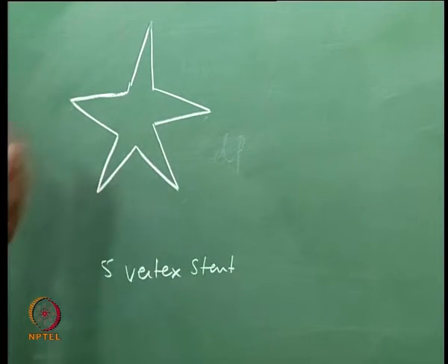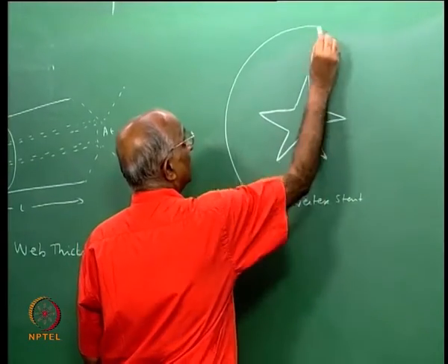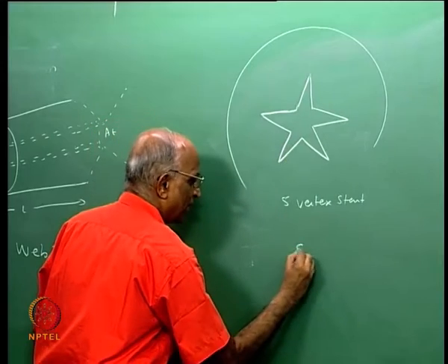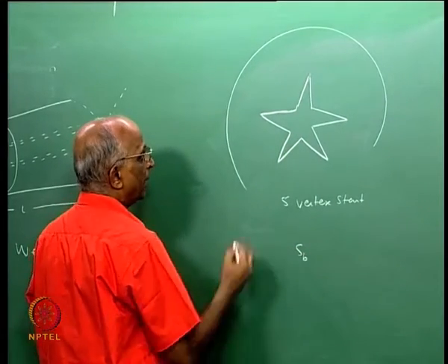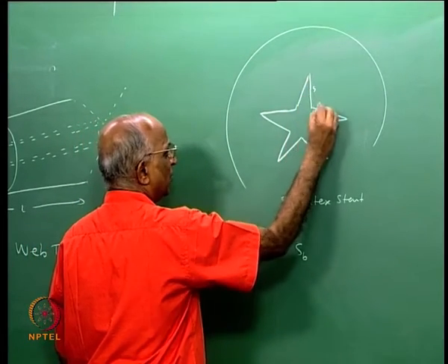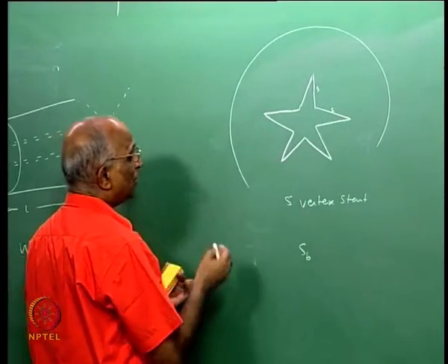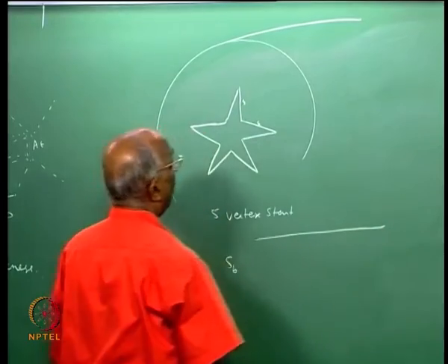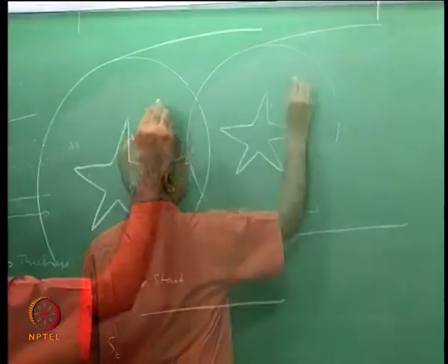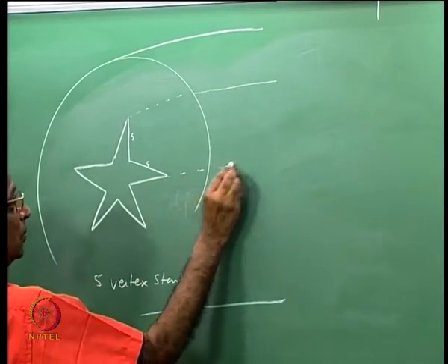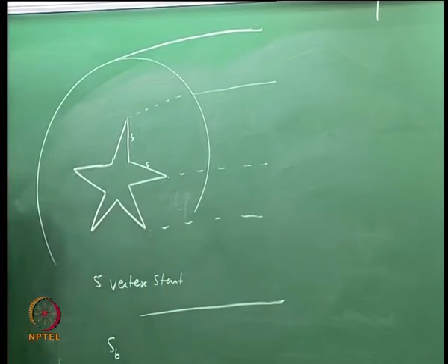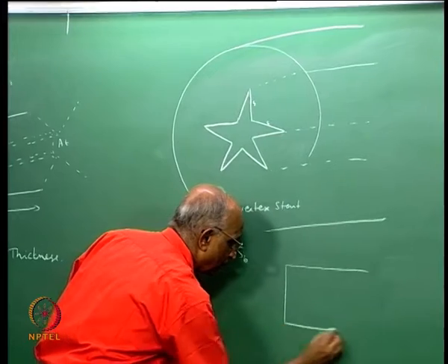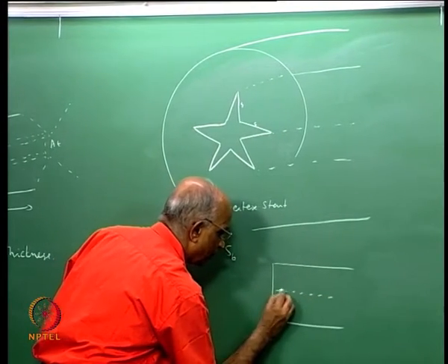How do I characterize this? That means my outer case is over here. I am interested in finding out how the burning surface area keeps evolving with time. Let us say that the sides of the star are S, and how does the grain look in the 3-dimensional plane? Well, this is my outer surface. Well, all these are points here, and therefore, if I were to make a plan view of this, I get a cylinder, I get this my center line.